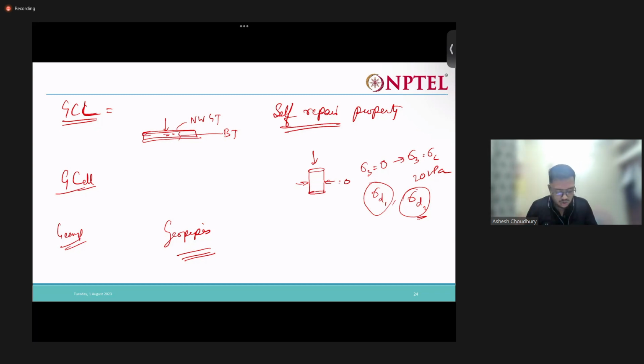These are columns made of stones, built inside the soil. There are some specific drilling devices with which these are made. So if these stone columns are encased by, say, geogrid material, what happens? It is seen that the strength and the rigidity of the stone columns actually increase.